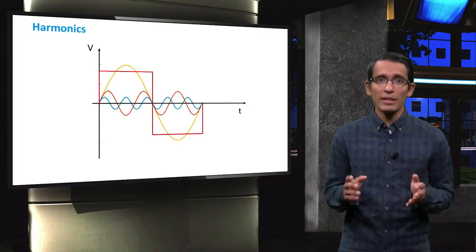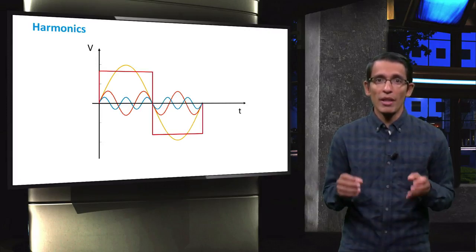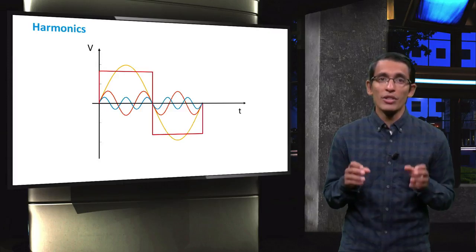All electrical appliances and generators produce harmonics and therefore are regulated under close standards. In large volumes, these harmonics can add up, causing interferences, malfunctioning of devices, and even fires. In order to reduce the harmonic content, filters can be used. Filters use capacitors and inductors, either in parallel or series, to cancel out the lower or higher harmonics from the output power.